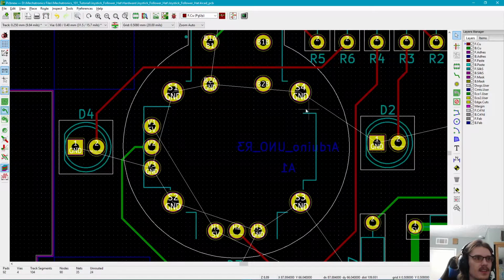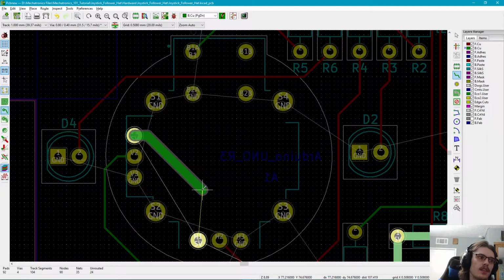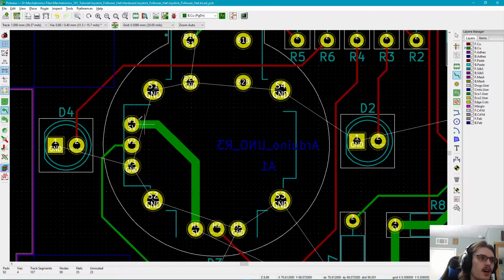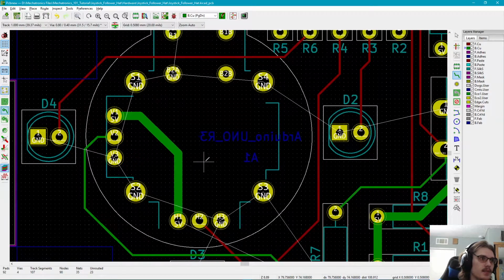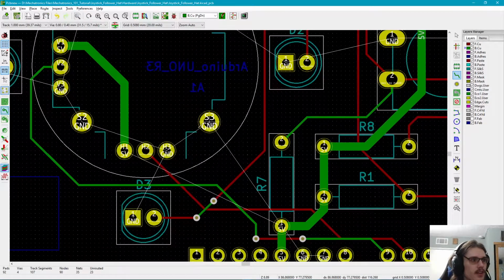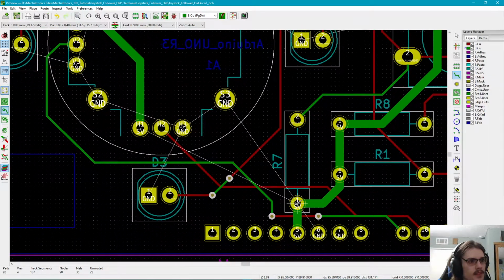My bad. Okay, so let's go back and fix that 5-volt. I should have mentioned this as well. We can route underneath, on the opposite layer of an IC or annoying component to desolder. So I have this on the bottom layer. The trace is running there, but not on the top layer, because I can access the bottom layer without desoldering the